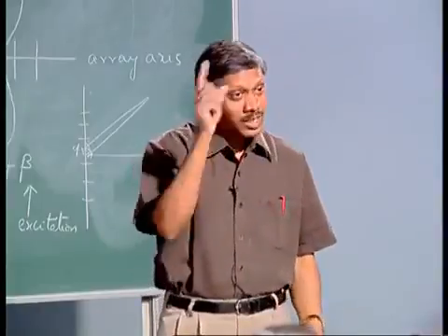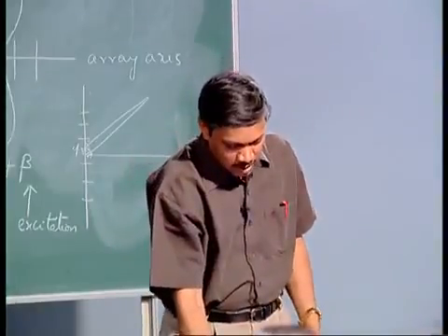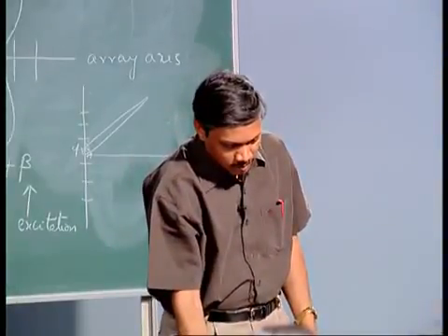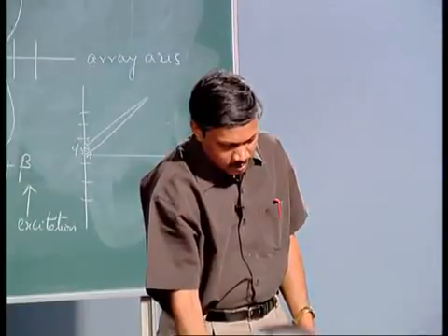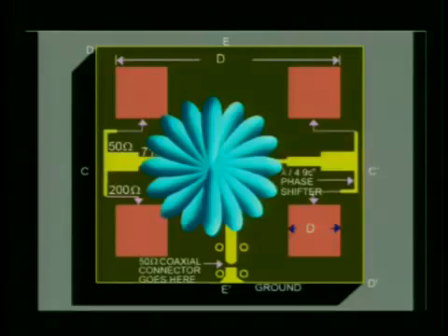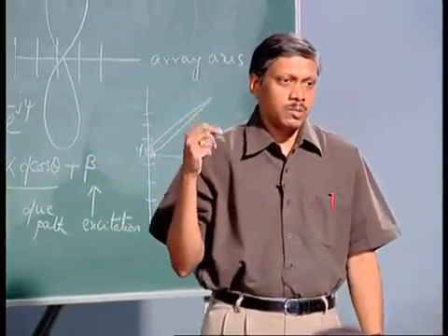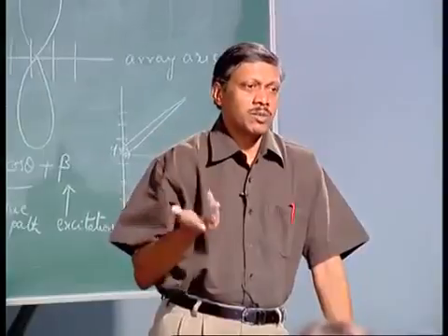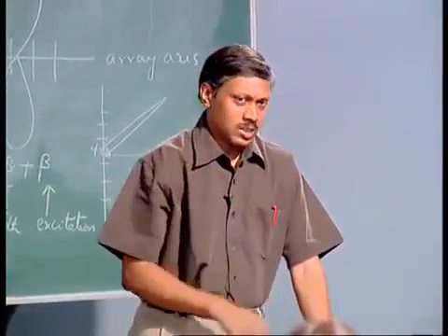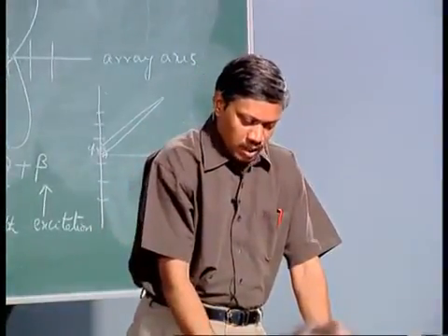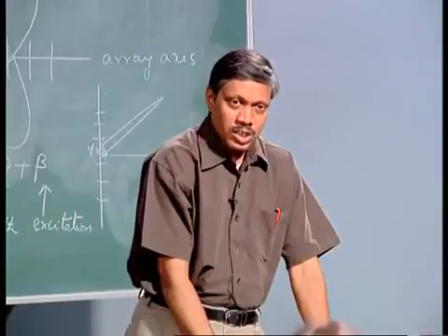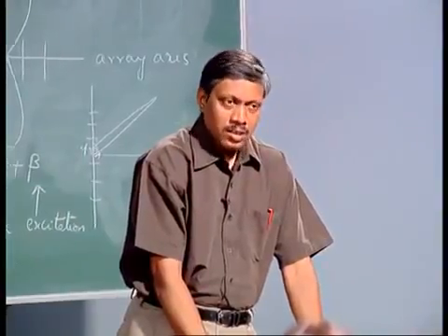In the previous slide, if you see, this is a situation of grating lobes, where almost all are of equal amplitude. All right. If you are having a lambda or 2 lambda type of separation, you will have this type of problem. So to avoid the grating lobes, you must keep your spacing between the elements less than lambda.